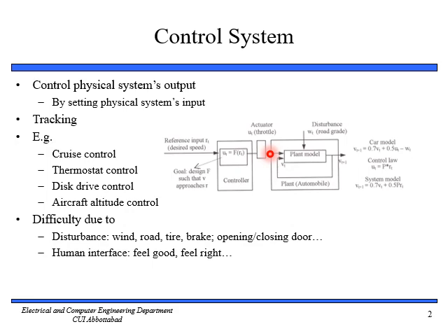The throttle is in your control. So we can increase or decrease the throttle in order to increase or decrease the speed. An external disturbance is acting upon the plant. You can see that we have road grade. If the road is not good, we have more external disturbances. If the road is okay, then we have minimum disturbance.